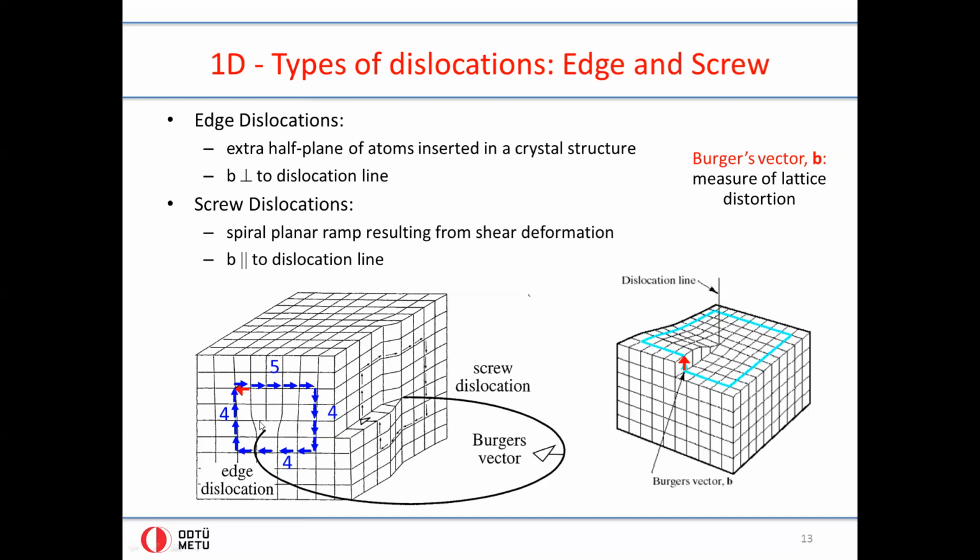And as you keep pushing, this bond here, or all of the bonds along the line from this point into the slide, will break, and they will rebond with this half plane, and this location here will have shifted to this point, and then with more pushing it'll shift here, and then here, and eventually the whole top portion of what was originally a square will have shifted 1 unit to this side, and this bottom portion will have shifted in relation by 1 unit to this side.